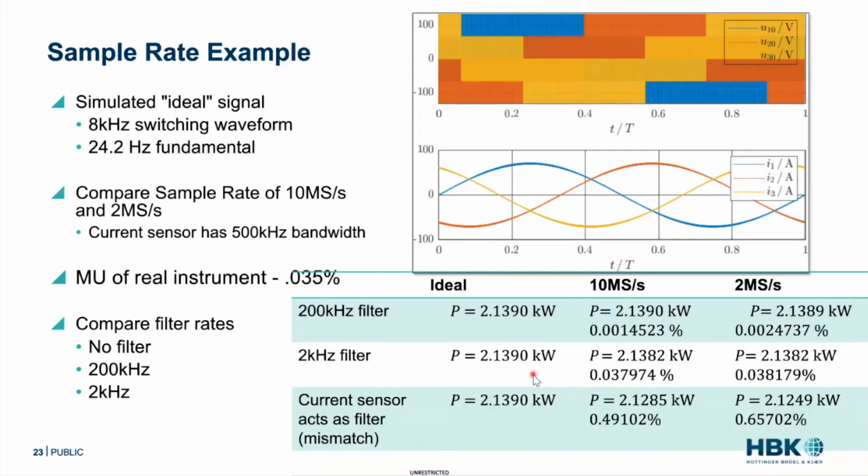I'm eliminating my switching frequency. And remember, this comes back to the fact that there's no real power in the switching. It's just losses. So if we're looking at real power, power delivered, that's all in the fundamental and the harmonics.